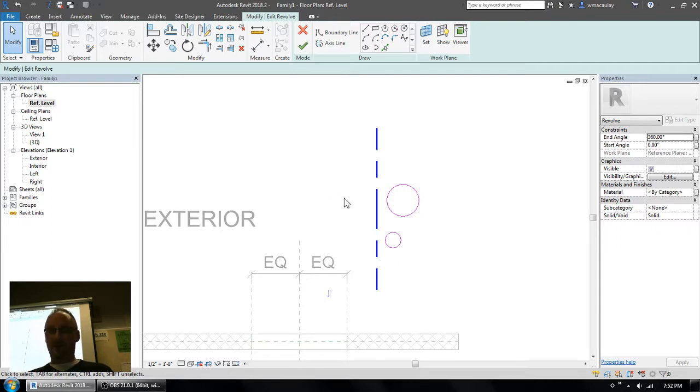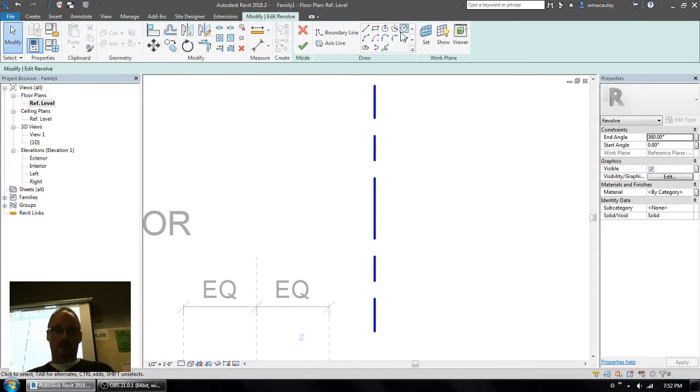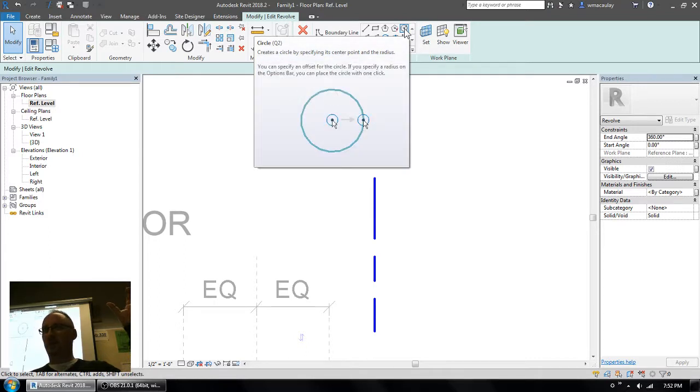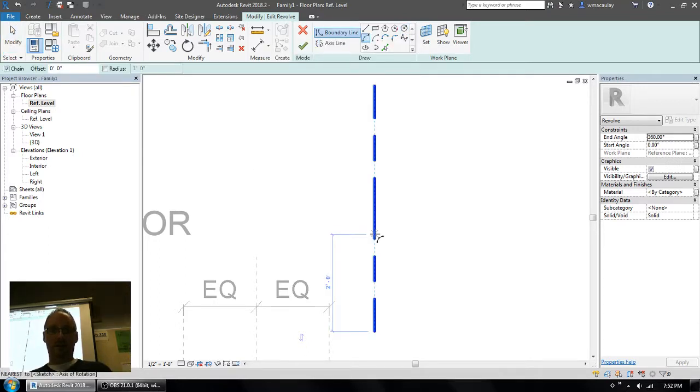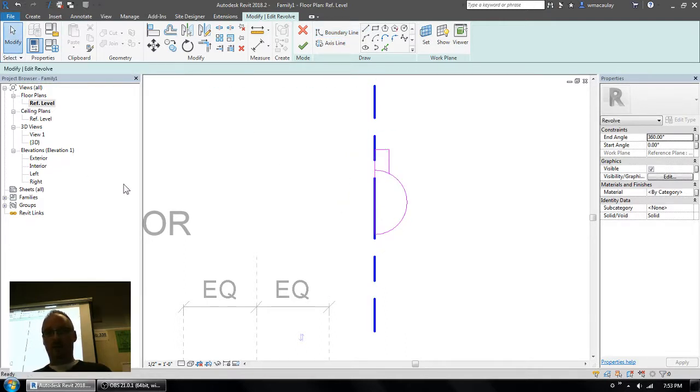Now, if I wanted to do something like a doorknob, for one of those non-accessible round globe style doorknobs, I would have to draw just an arc, not a circle. So I draw an arc right on the line. Now, to draw the part of the knob that goes into the door, I just draw a straight line for that. Then I would return back into the axis of rotation and finally come down the axis of rotation to where I had started. Now this is not valid because this form here is self-intersecting, so I need to grab this little curve here and just pull it back.